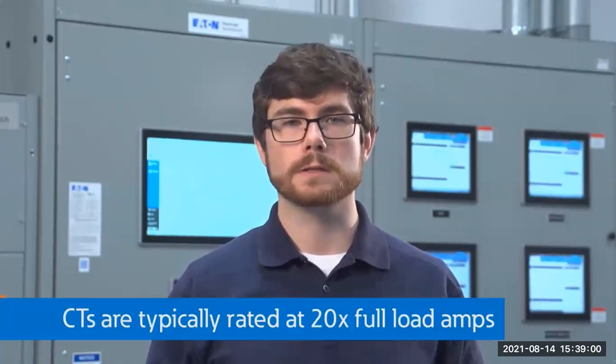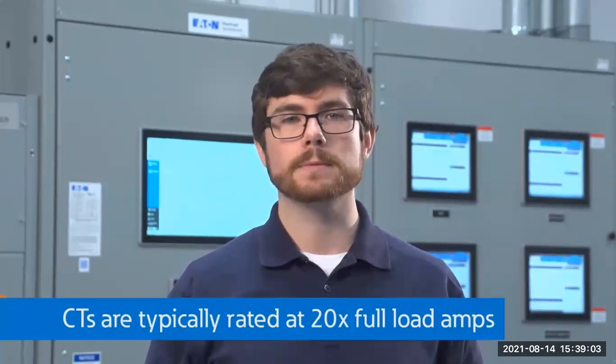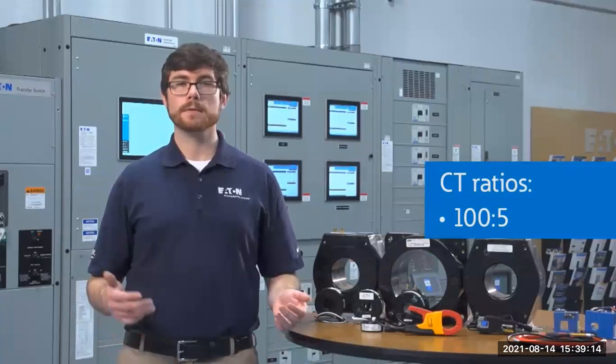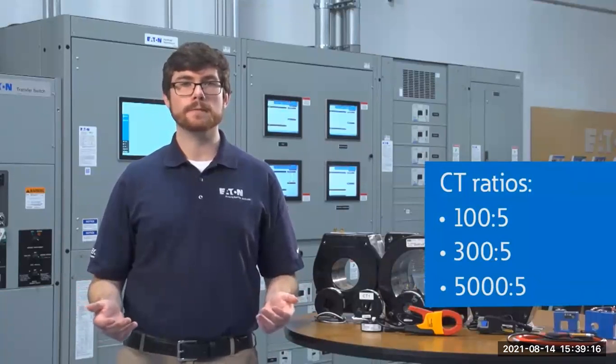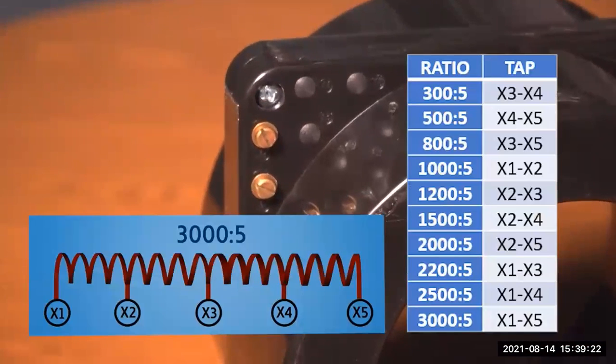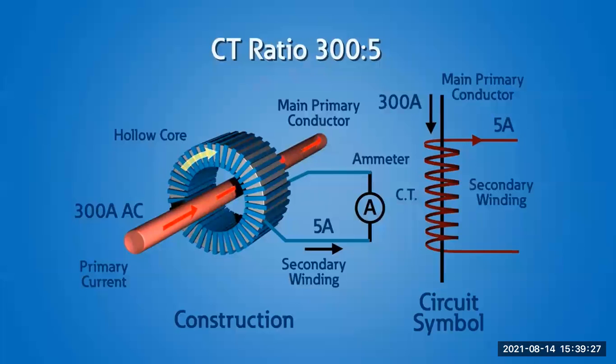For all protection applications, CTs must be rated to accurately measure the high currents that are possible during fault conditions, usually 20 times full load amps, so that the breakers can trip in the proper sequence without saturating, which yields an incorrect result. CTs come in many different ratios, such as 100 to 5, 300 to 5, 5,000 to 5, 60 to 1, and some have multiple taps where the ratio can be selected in the field or for a specific application. Let's take, for example, 300 to 5 amps, meaning that a wire carrying 300 amps AC flowing through the core will produce 5 amps on the secondary winding.